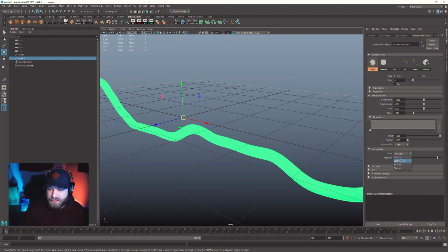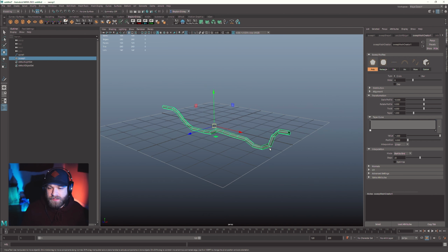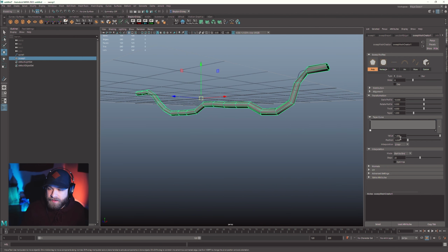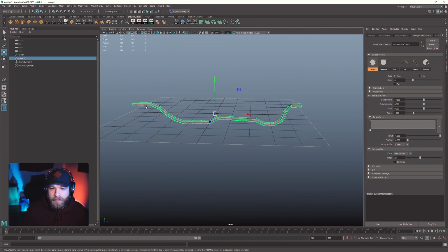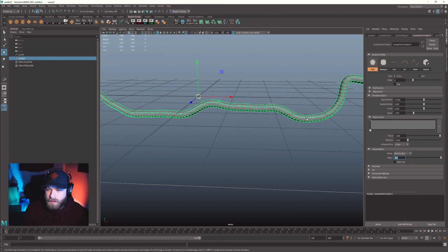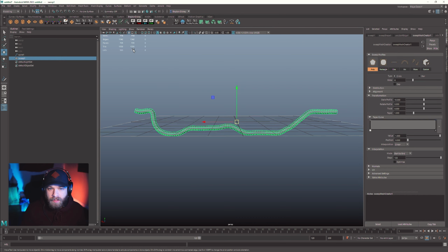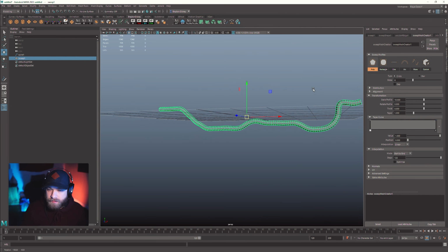But what I actually tend to use is the start to end tool, which is very similar to the curve tool when you go to rebuilding the curve and you can choose the number of spans. This is just going to show how many divisions it's going to have from beginning to end. So I'll set this usually to something like 64, a power of 2 of some kind, which will allow you to really fine tune how many points are being used to make up your curve.